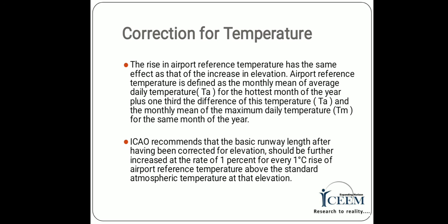ICAO recommends that the basic runway length after having been corrected for elevation should be further increased at the rate of 1% for every 1 degree Celsius rise of airport reference temperature above the standard atmospheric temperature at that elevation.